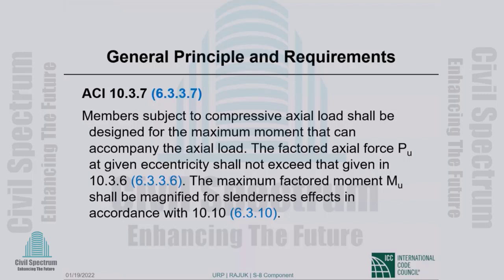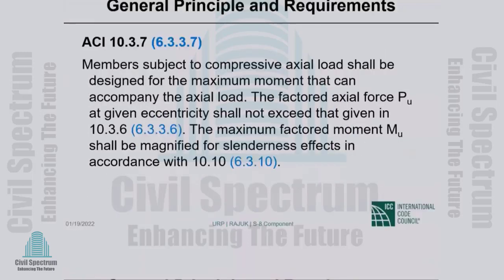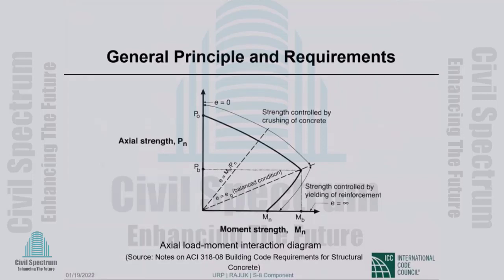Now, if it is a slender column, in one of the approaches that we use for the design of slender columns, we magnify the moments that are actually applied by the loads, as you will see in later parts of this presentation.